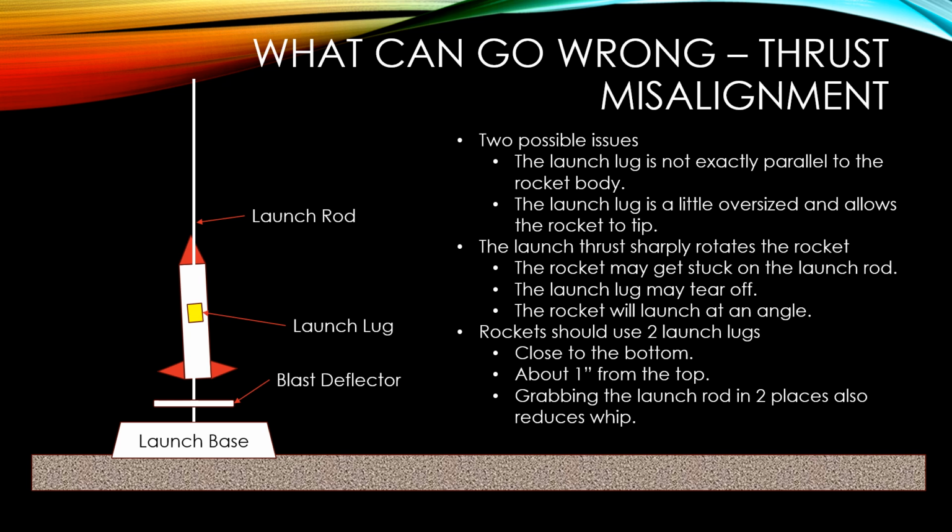Now, there's a lot of comments on how to really fix this. One of them is to just use a much longer launch lug, and yeah, that'll work. Another is to make sure that you use some heavier duty glue. And I myself use polymer glue, so it's attached quite well. But still, the stress on the launch lug is extremely significant right at the time when the engine ignites. And if this is not a smooth transition going upward, it's just going to cause some issues.